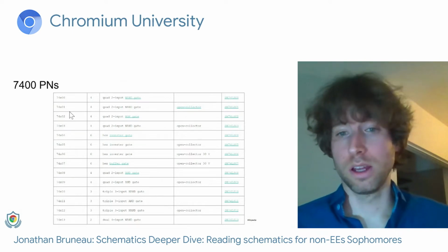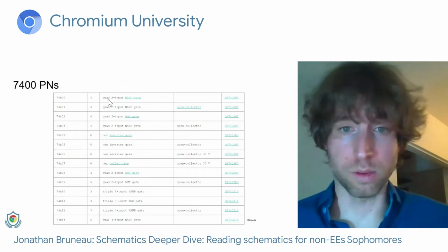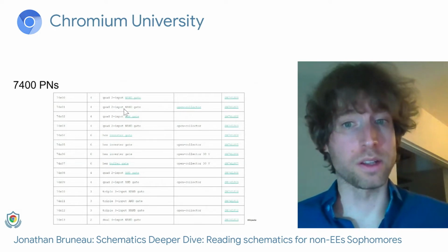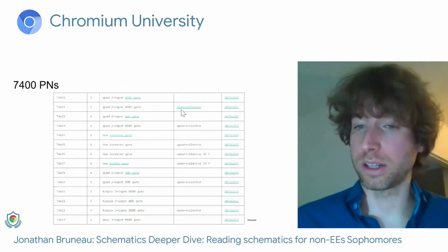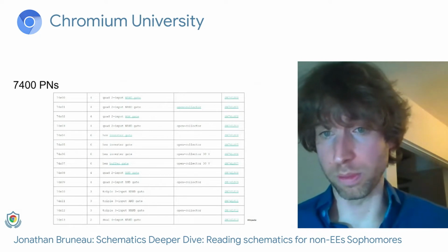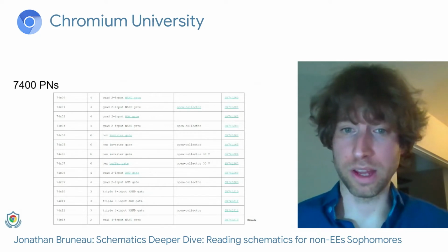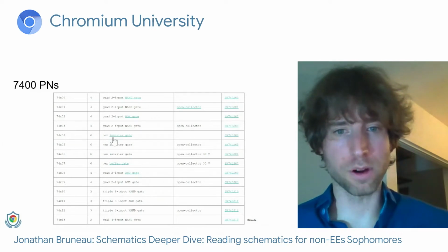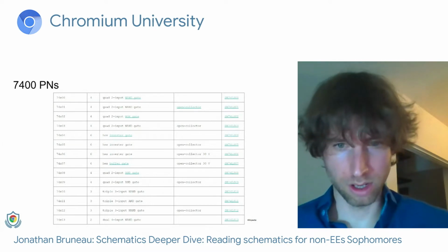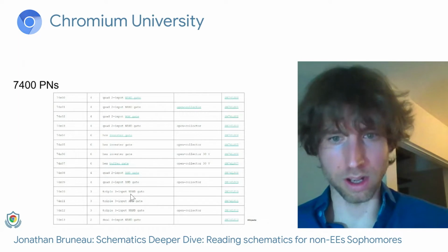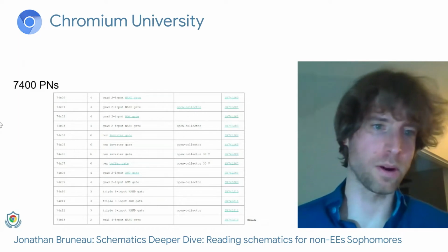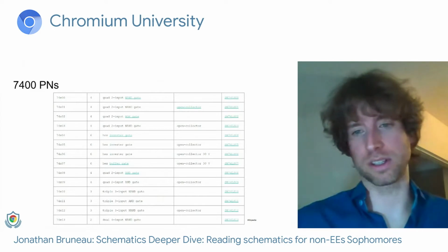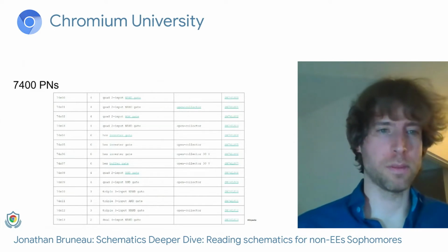And just looking at this quickly, we have the quad 2-input NAND gate, but we also have the quad 2-input NAND gate as an open collector, which is a synonym for open drain. We talked about that in our last talk. There's a 6 inverter logic chip, right? There's a triple 3-input NAND gate, etc.